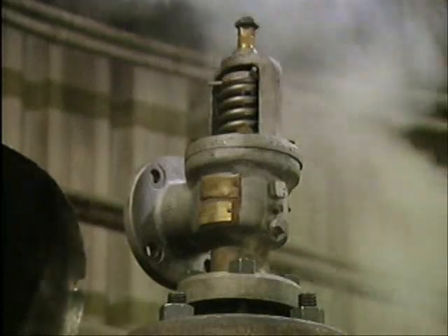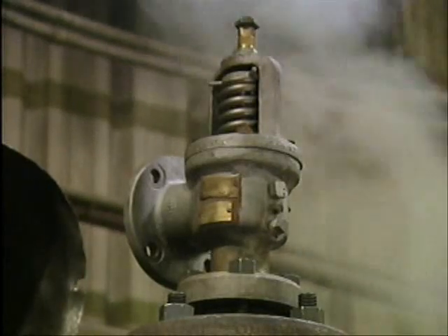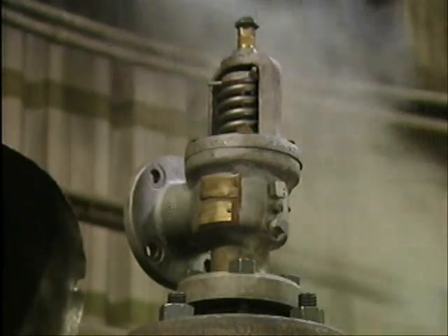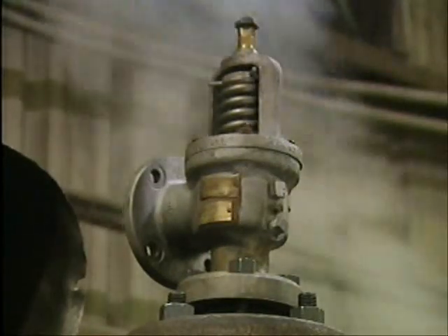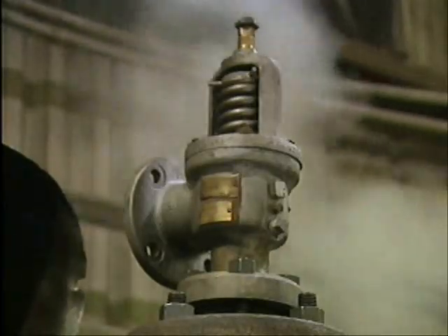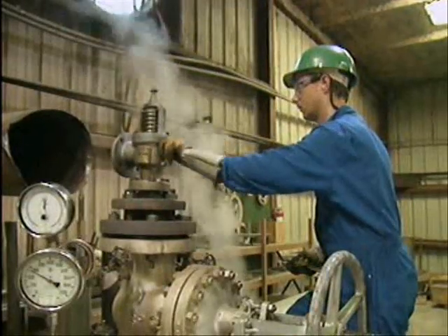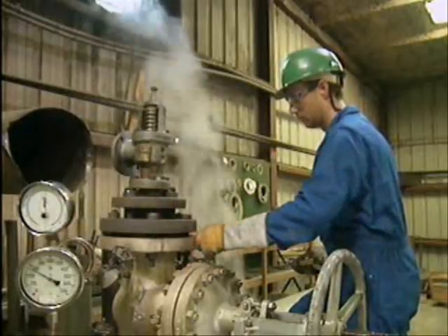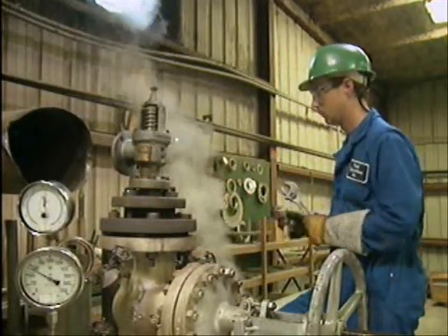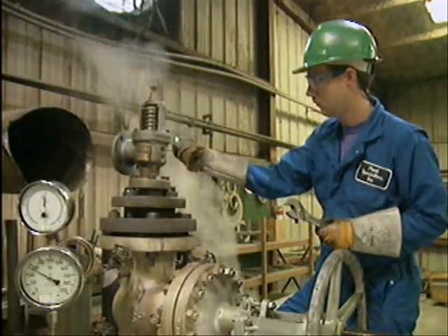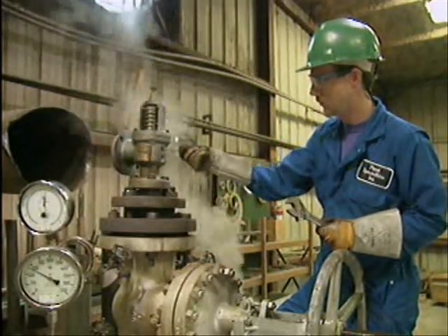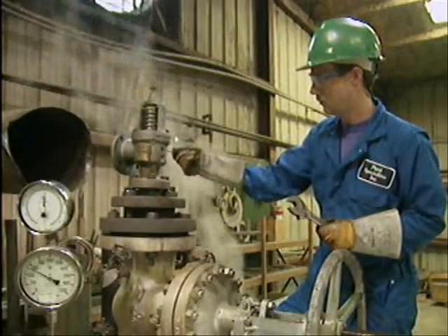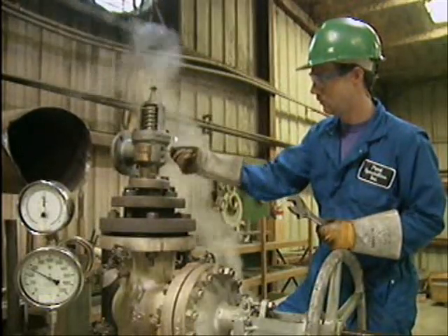After you've adjusted the compression screw, test the valve again to see if it's been set properly. Usually, you need to make several adjustments and tests to fine-tune the set point of the valve. If testing indicates that blowdown has been changed, you'll need to readjust it. To make blowdown adjustments of this huddling chamber safety valve, you must raise or lower the adjusting rings until the blowdown is within specifications.